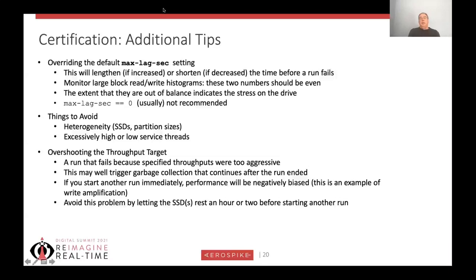You don't want to immediately start another run. The reason is, if you're pushing the drive hard, you may well have triggered garbage collection. The thing about garbage collection is it's a background process, but it can also be going on even if you're not putting any load on the drive at all, because if you drove it really hard, it could be trying to catch up.